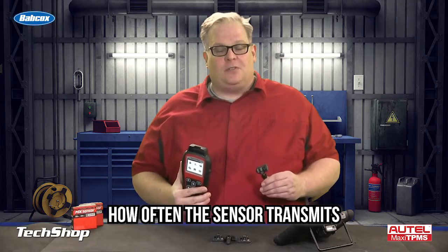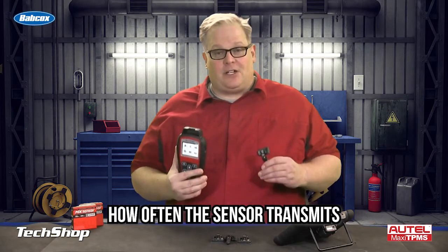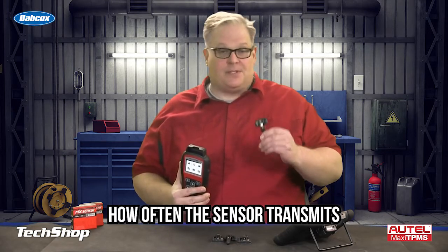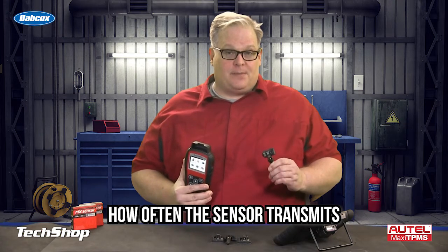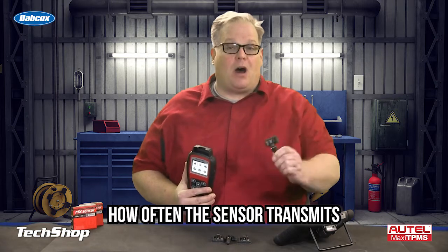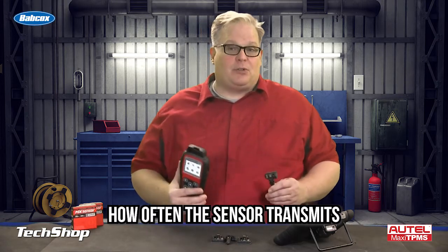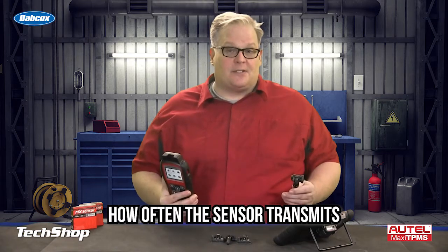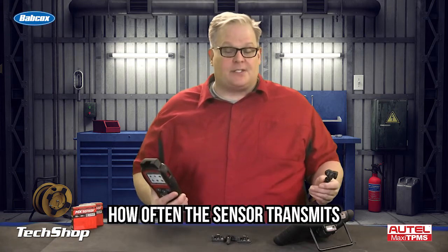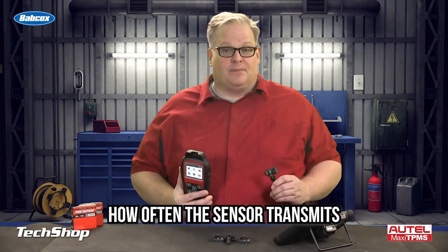The next thing it's setting is the language that it's speaking to the vehicle in. This is typically code, and this basically determines when the sensor is going to transmit, what information it's going to transmit, and also how often it's going to transmit to the vehicle. It could be different: a Toyota could transmit every 60 seconds, a Porsche every 20 seconds, a GM vehicle every 30 seconds. This is what's programmed onto the sensor.